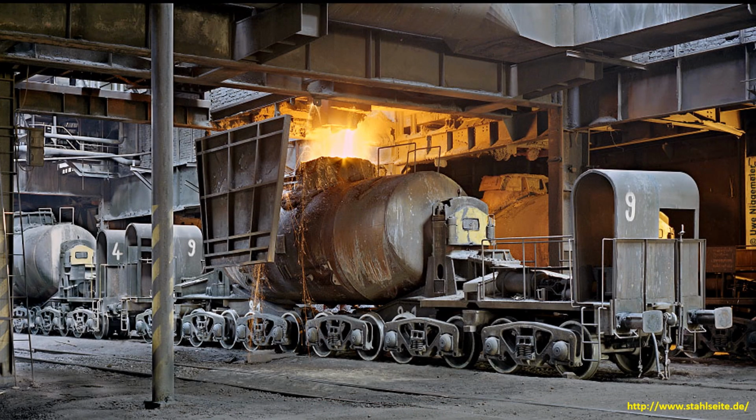This is a bottle car that's on a rail line. So basically the pig iron is being tapped from the bottom of the blast furnace and is flowing down into this bottle car, and then the pig iron will be transported to a different part of this steelmaking facility. It'll either be cast into ingots or it'll be dumped into a basic oxygen furnace and combined with other elements to form steel.